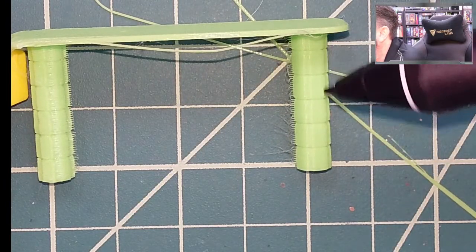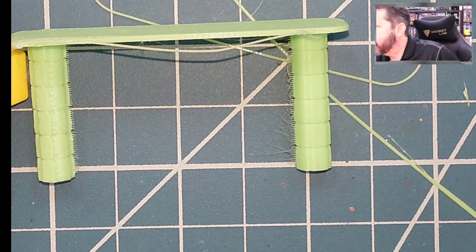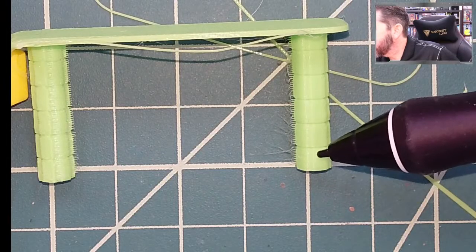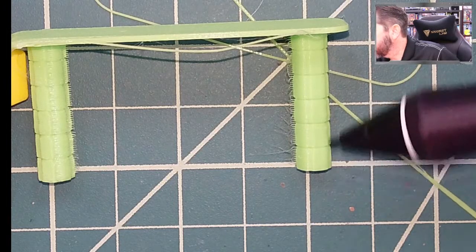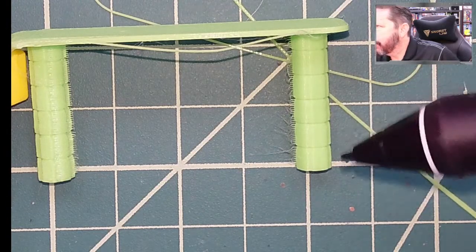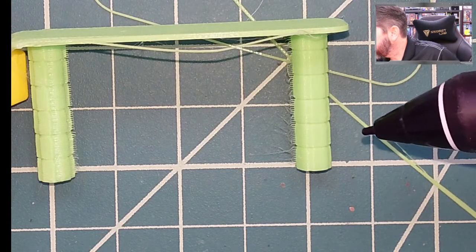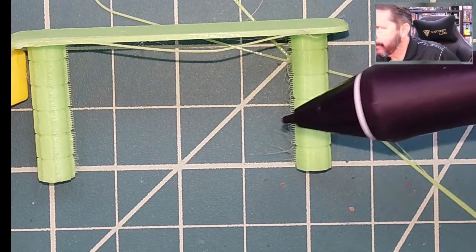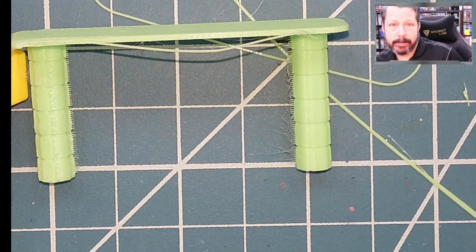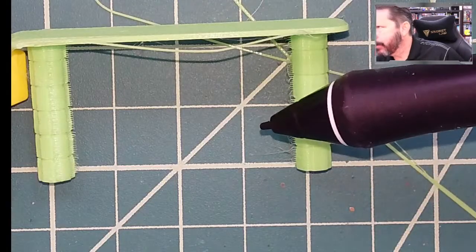So those bottom three are the 0.5 millimeter retractions and the different speeds. And they do seem to be a little less noticeable on the 1 millimeter. They're still there though. So probably what I would do is turn Z-Hop on and see if that fixes those. That might be a better way, because the settings are all about the same, and we're really zoomed in.